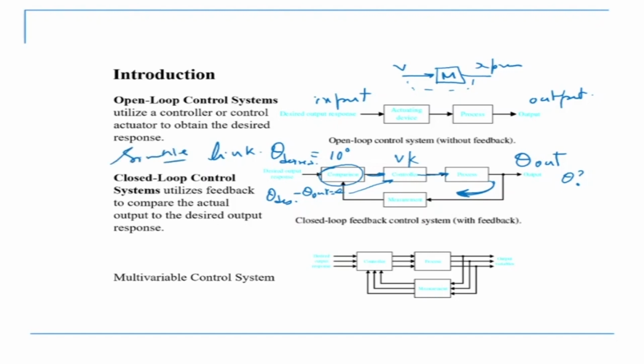And when I talked about sensors and actuators, I talked about independent joint control. That means there is one control loop for each joint and they are not connected with one another. It is like they are all independent.